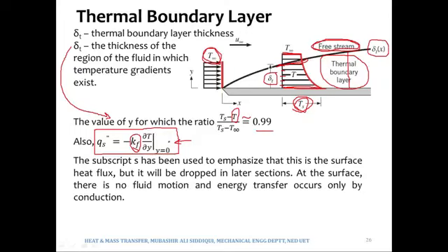This is the expression for conduction. Kindly remember that the very first layer of the fluid, which is in direct contact with the surface, would have the same velocity as that of the surface, and the heat will be transferred via pure conduction to the very first layer of the fluid, which sticks to the surface, no slip condition.